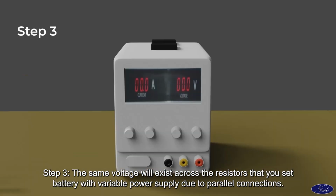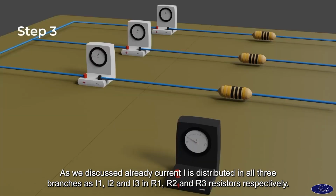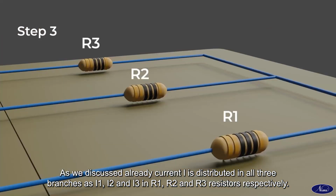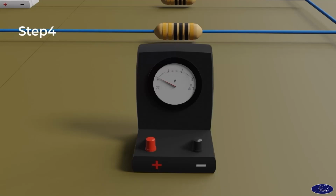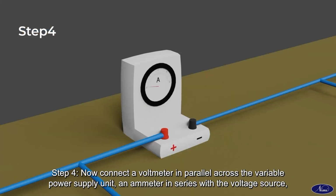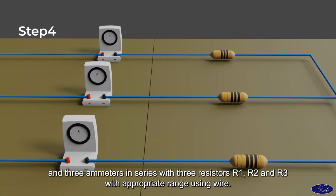Step 3. The same voltage will exist across the resistors that you set with the battery or variable power supply, due to parallel connections. As we discussed already, current I is distributed in all three branches as I1, I2 and I3 in R1, R2 and R3 resistors respectively. Step 4. Now connect a voltmeter in parallel across the variable power supply unit, an ammeter in series with a voltage source, and 3 ammeters in series with three resistors R1, R2 and R3 with appropriate range using wire.